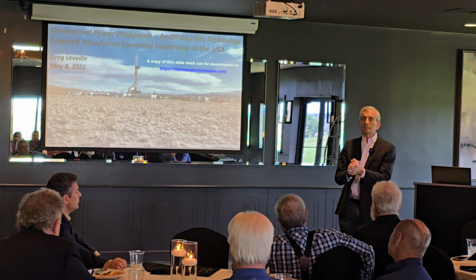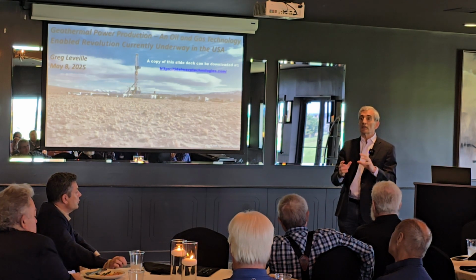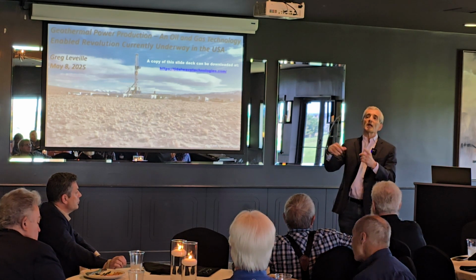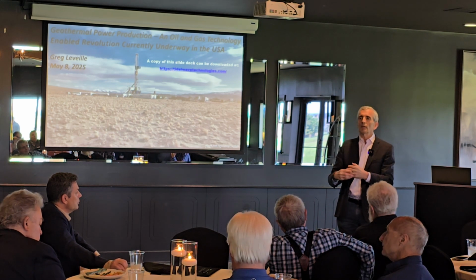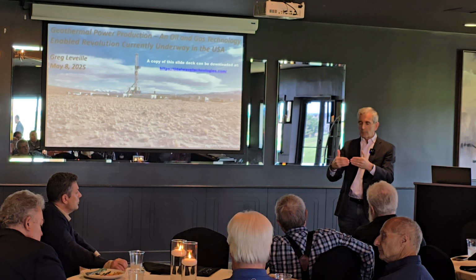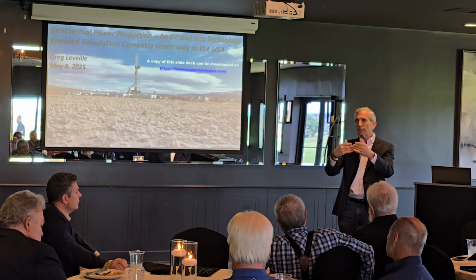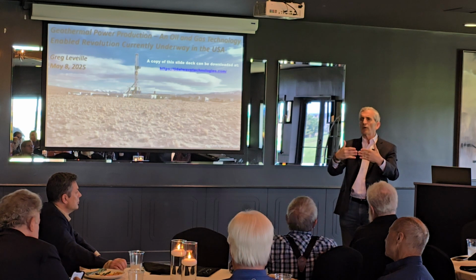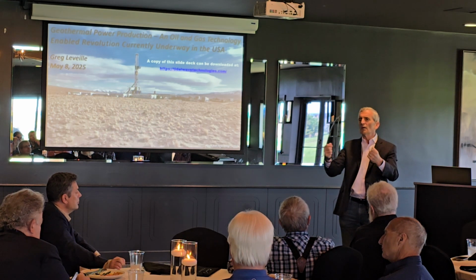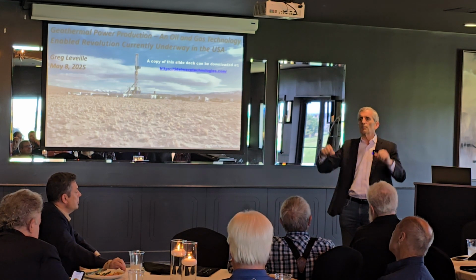Yeah, so let me answer that first for EGS and then talk about the others. As I mentioned at the outset, the way EGS had been done, degradation was a huge problem. You were creating one fracture plane or a closely spaced group of fracture planes, pumping tens of thousands of barrels of water into it, and literally in months to a year or so, you were starting to get a lot of cold water at your producers.